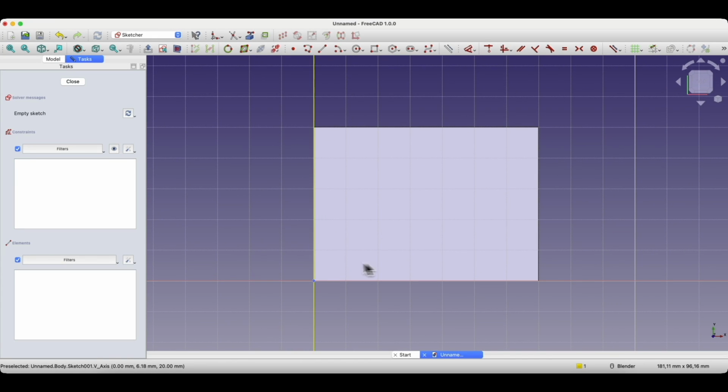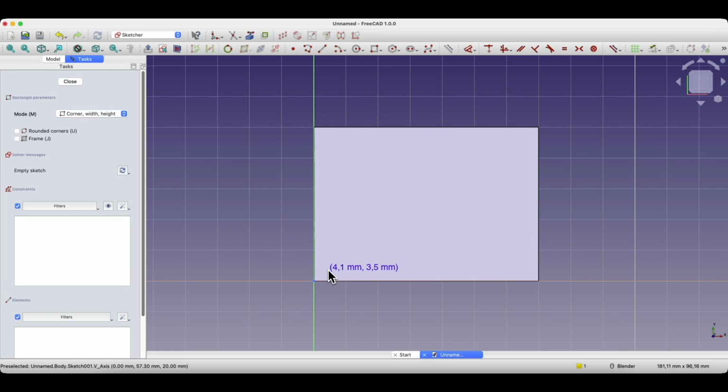Now this face becomes the sketch plane. Here I will create 3 pockets. We will also use the rectangle drawing command. Select this command and place the first corner of the rectangle roughly here. Regarding the dimensions of this rectangle, we will enter 15 mm for the x-axis. I press Tab to switch to dimensioning along the y-axis, and for the y-axis, I will enter 40 mm here.